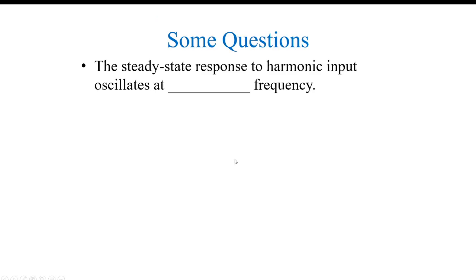So let's see some questions. Let's see if you can answer this. The steady state response to the harmonic input oscillates at what frequency? Of course, at the input frequency. What I'm trying to say here is that your natural response, your natural frequencies, will disappear if you wait long enough.